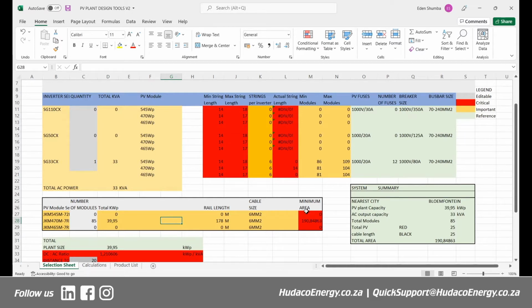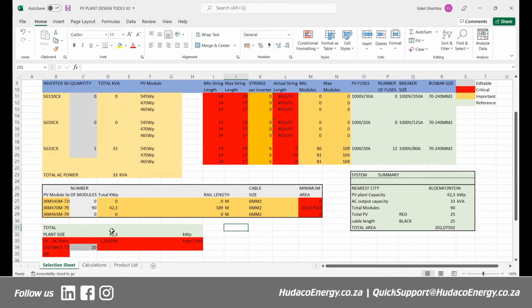Right. So now I've just used the 470, and now let's say I put 90 panels. For example, I put 90 panels. You can now see that my string length has gone up to 15. 15 is still within the range of 14 to 17, but there's a bit of a challenge in the sense that we are now going above the recommended DC to AC ratio. We're now at 1.28.